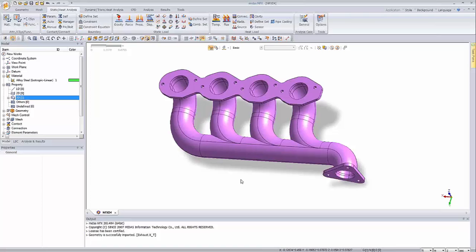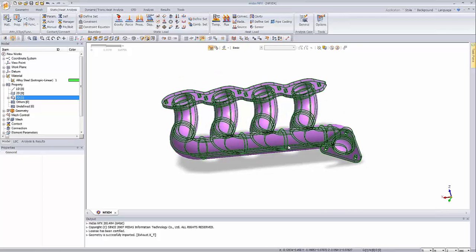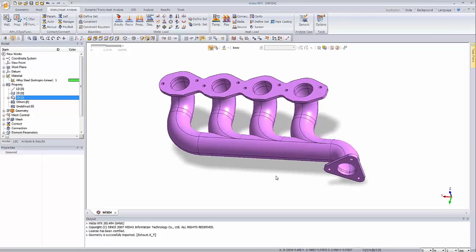Help comes from our selection toolbar. This is a very useful tool, and I will show you how to use it efficiently. Our task is to select all of these inner faces from the pipes. The selection toolbar consists of a few parts. The first part describes the selection mode, so you can select entities or deselect entities. At this moment I will leave this option as it is.